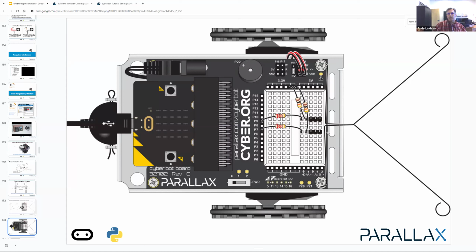And then this row of 5 is going to have a brown, black, orange, a 10 kilo ohm resistor in its socket. And we want everything to sink in at least 1/4 of an inch. And then a red, red, brown in the socket too. Now the brown, black, orange is going to go up to 3.3 volts, one of these black sockets up here. And then the red, red, brown is going to go over to the P7 socket. And again, that also is a black socket.